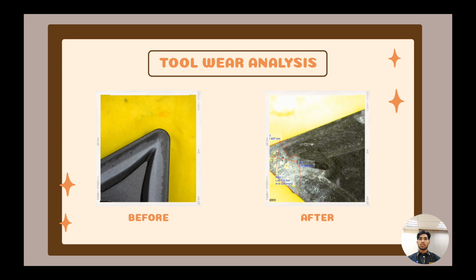The third picture shows the top of the lead cutting tool that has not been used. If you look closely, the surface of the chip breaker has no traces. The fourth picture shows the lead cutting tool that has been used for the lead process. In the picture, if you look carefully, it has an effect called crater wear. The crater wear on the point of the tool is 3.535 square millimeters.